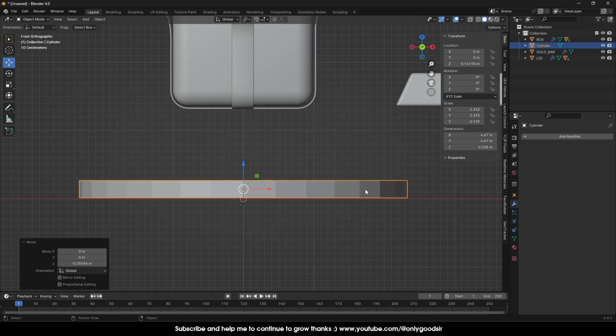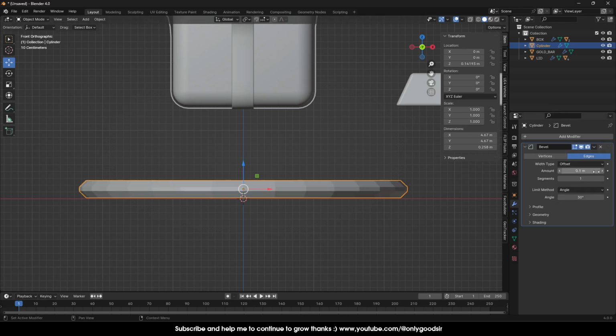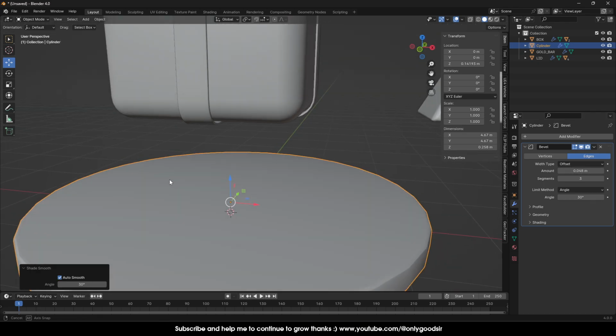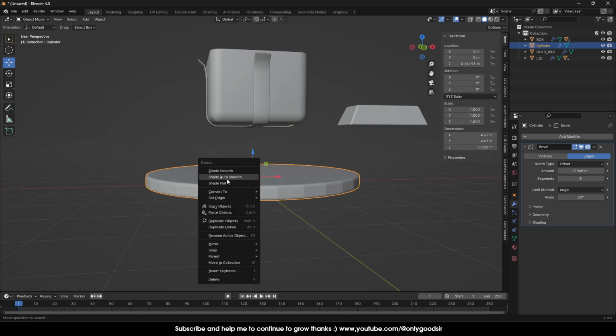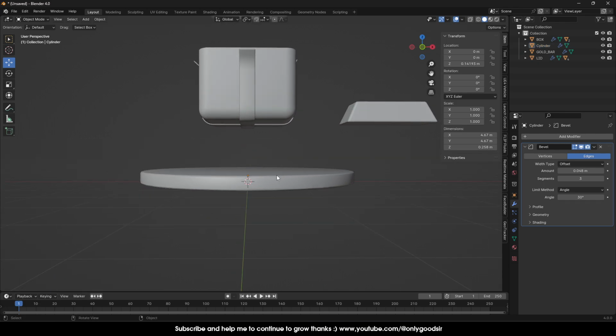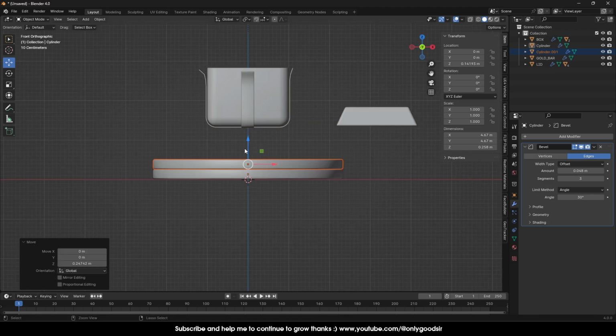Now before I do anything, I want to apply some modifiers to this. So again, Control A, apply the scale to that, then apply a bevel modifier to that. There we go. Nice rounded edge. Now if I say shade auto smooth, it's pretty nice. Nothing too bad. Oh, don't undo. I accidentally pressed undo. Ignore that. Anyway, Control C, Control V, and Control C, Control V.